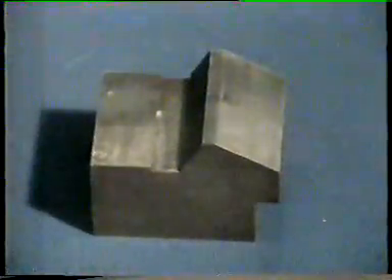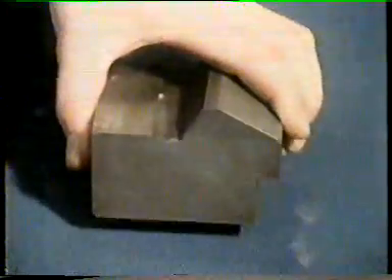First, the metal surface is heated to about 900 degrees centigrade, in this case by a row of high-temperature flames moving slowly along the slideway. The hot metal is then cooled rapidly with water. This heating, followed by rapid cooling, hardens this particular material. If we look at a specially prepared cross-section through the slideway, you can just see the hardened area around the edge.